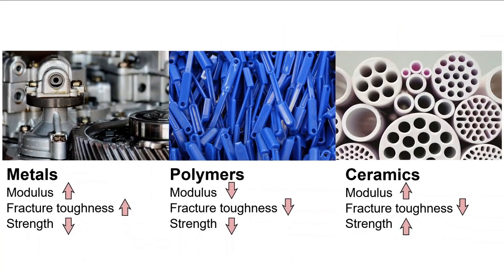We haven't covered ceramics specifically in this course, but we have described material properties that can be attributed to them. For example, an extremely brittle steel can exhibit the same type of behavior as a ceramic. Generally speaking, ceramic materials have extremely high strength and moduli, but are equally extreme in their intolerance of any type of flaw, as characterized by having a lower fracture toughness than even polymeric materials.